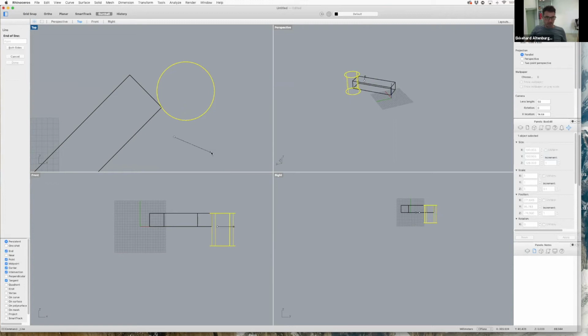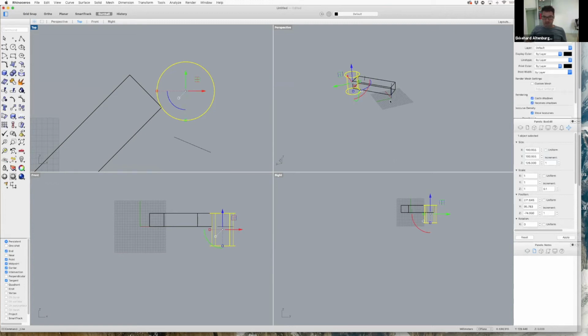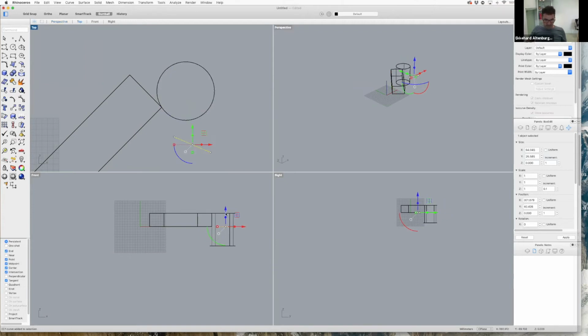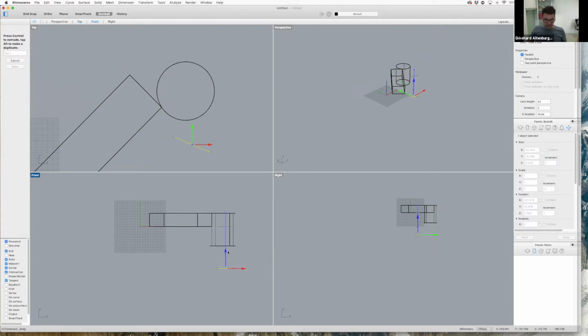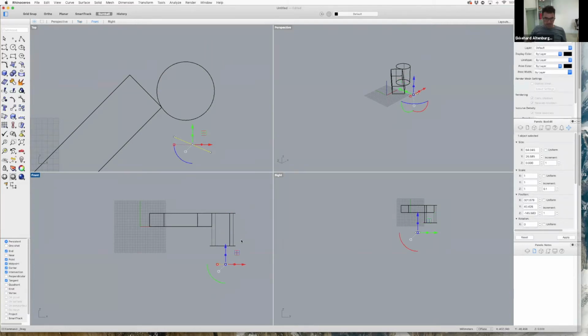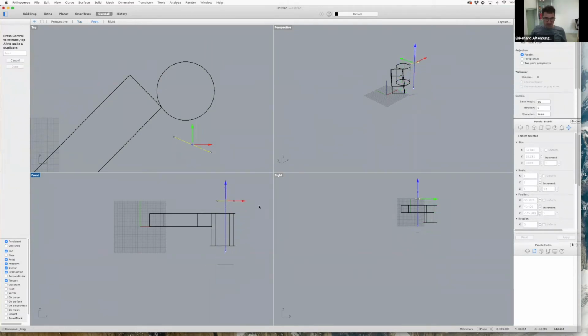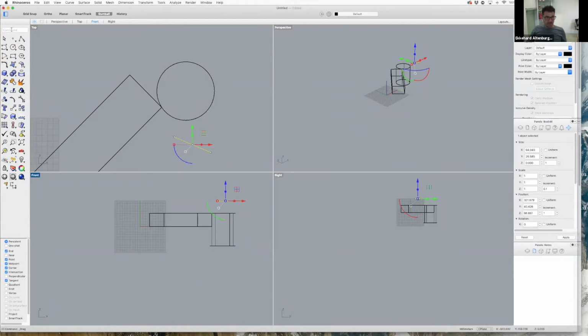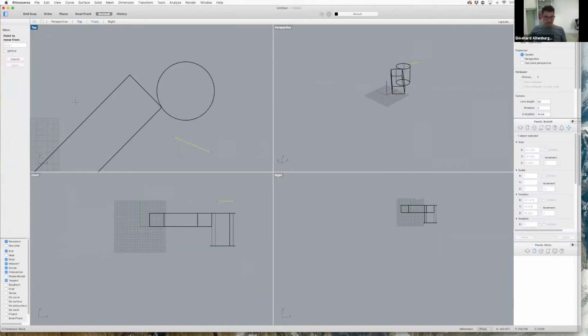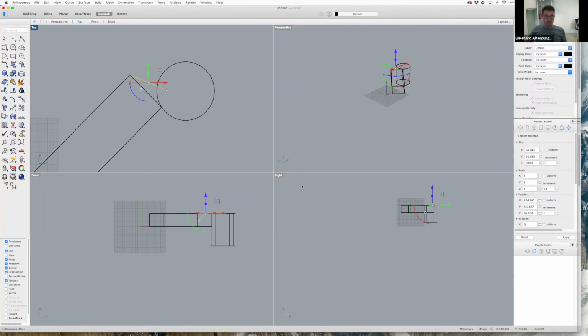let's draw a line. Okay. So when you look at it, where is this line now? I activate the line, or the line is obviously there. You can move the line there, but also you can type in the command move. And you press enter, and then you can move it, let's say, from here to this corner.